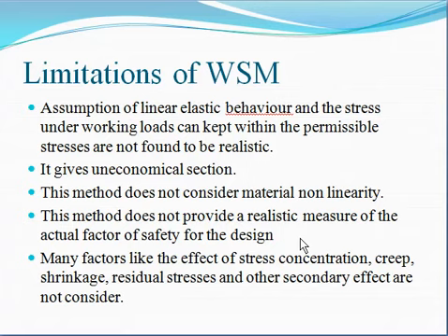Next is shrinkage. Shrinkage is nothing but the volume change, the effect on the structure due to temperature. This is also not considered by this method. And other points like residual stresses and other secondary effects are not considered by this method. These are the limitations of the working stress method. That's why, there being a large number of limitations, this method is outdated and not used right now.